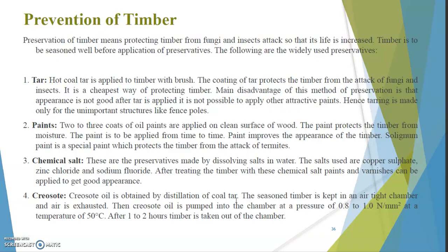So if you want to apply this creosote oil, you have to send a stack of timber inside a closed chamber, and inside that closed chamber people with full masks and lab coats will pump and forcefully apply that creosote spray onto the surface of your timber in such a way that it covers all the surface of the timber.